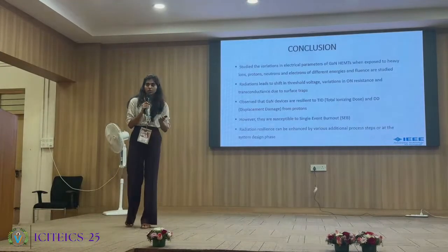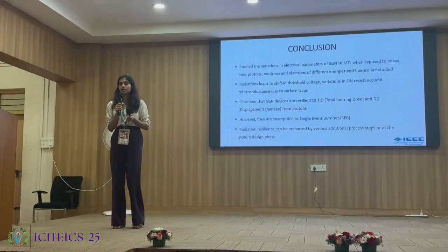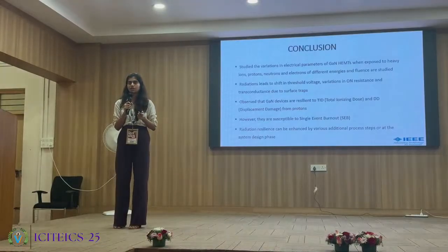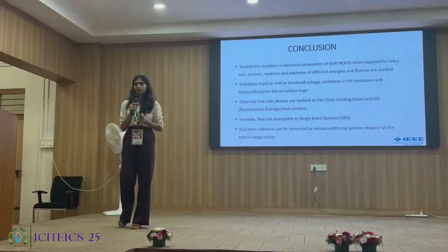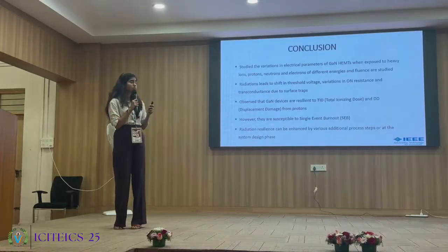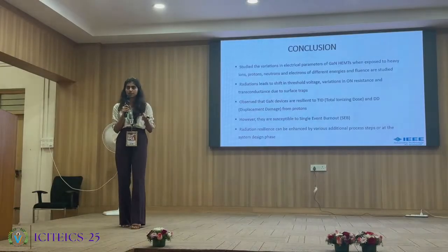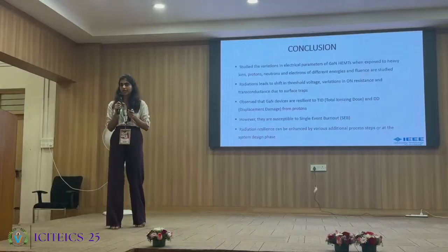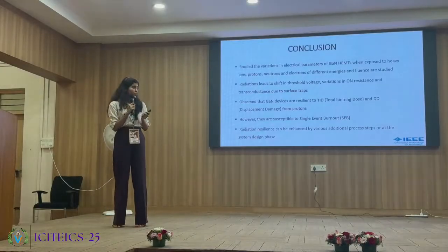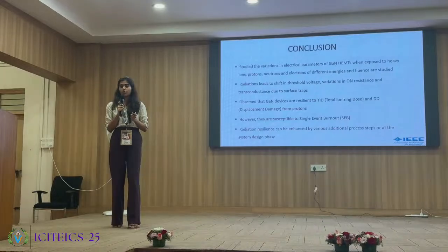We move on to the conclusion. Our study suggests that while the gallium nitride devices are being resilient to total ionizing dose and the displacement damage from the protons, they will remain vulnerable to the single event burnouts. Because of these radiation effects, there will be shift in the threshold voltage, on resistance, transconductance, and many more characteristics. This is mainly because of the trap dynamics, which are responsible for altering the device's electrical power.